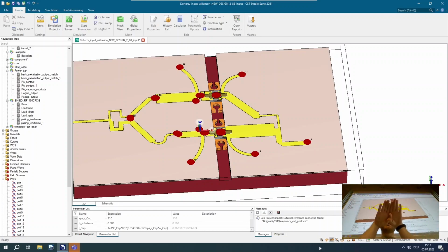And when you make that as compact as possible, compact and coplanar don't go together. Coplanar is usually a very wide range of operation. Sure, you can reach a lot of impedance points by being independent of the substrate. True, you do a non-grounded coplanar, where you use the reference as your ground side, and by varying the distance of your virtual ground with respect to your middle carrier, you can achieve a lot of impedance points,